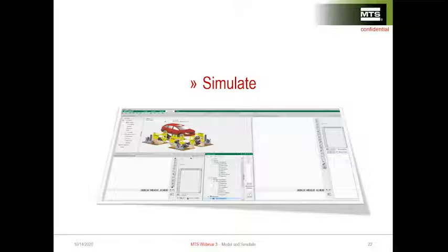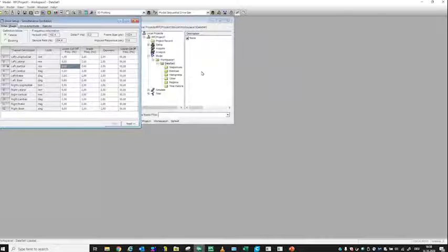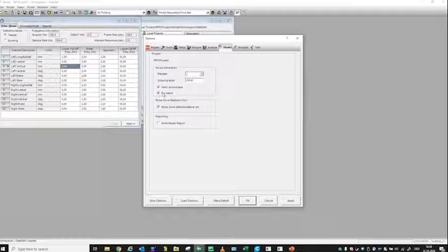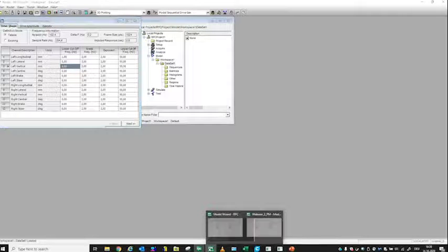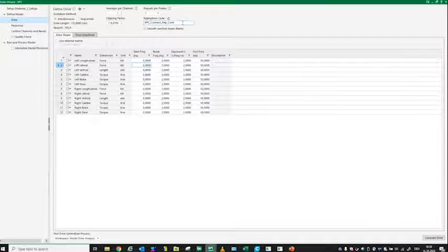If I get the question right, the person is asking about the fixed seeds we have here, right? I hope I got the question right. The fixed seed is always creating one white noise with the same random signal. In RPC Connect, this is the replication code which you see here. If I type in, let's say 1, 2, 3, 4, it will generate a fixed seed, so to speak, so one white noise with a random time signal. And if I type it in any other project, or in 10 years later, I type in the same number, I will get exactly the same white noise.